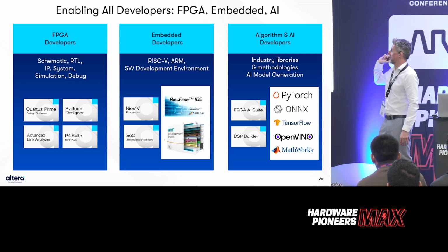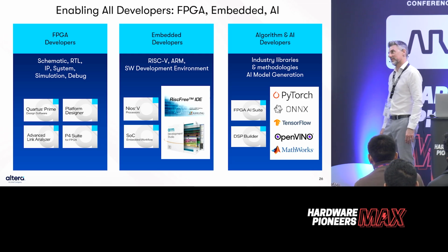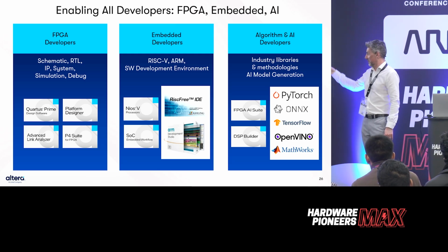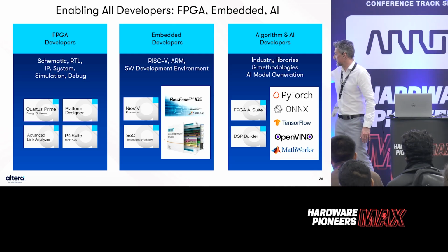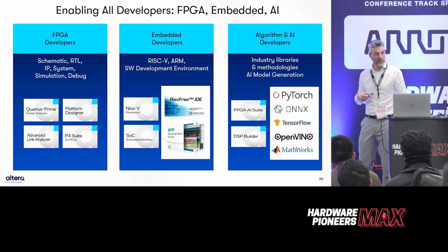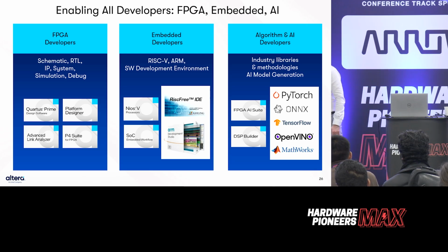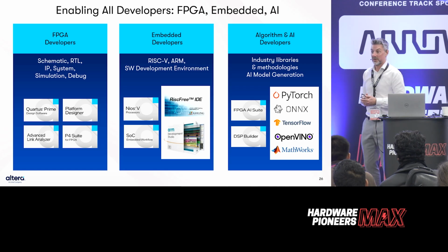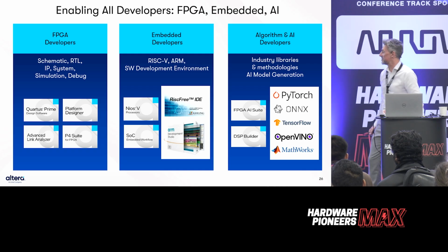And then George's favorite, AI. So we've tried to keep it quite generic. If you are looking at some kind of edge inferencing, all the standard models, we can split that out. And we use the Intel OpenVINO tool as well. So you can take, say, a TensorFlow model you've got, put it through OpenVINO, and it will spit out an optimized model, which then goes through our tool here to fit into the Quartus flow, effectively generating a bit of black box IP for you. So you don't need to know too much about the way the FPGA works. There's tools available if you're looking at edge inferencing.